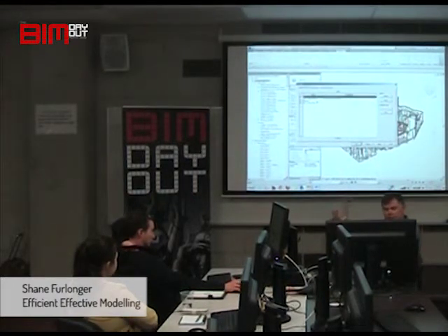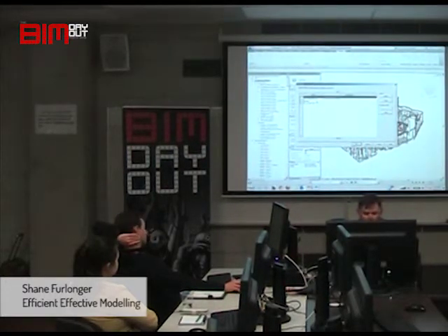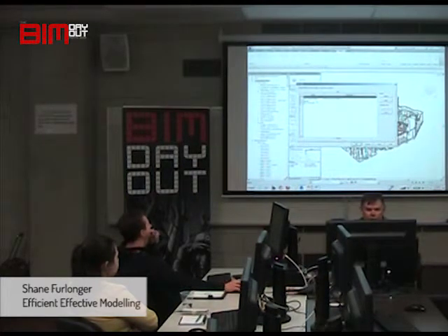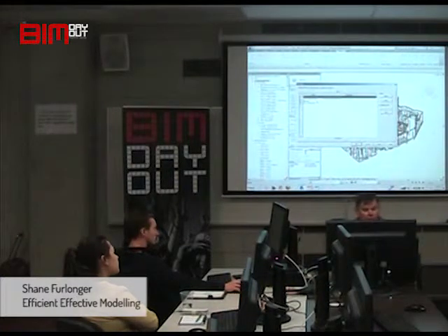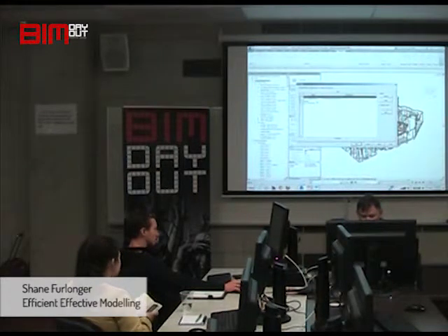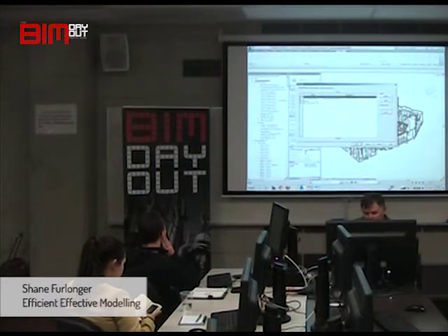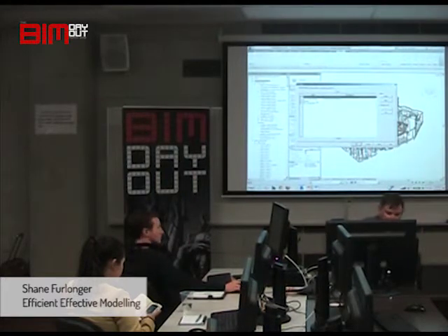You want to have structural steel set up in a different way for some reason, whatever that may be, just to work things out. Also, it's a really good way of doing windows, to have windows in what we call a legend view or legend phase. What you do is you set up your two phases. It's curtain walls versus windows. Yes. You set up your legend, your two phases, call them whatever you like. I call them legend and demolish legend.